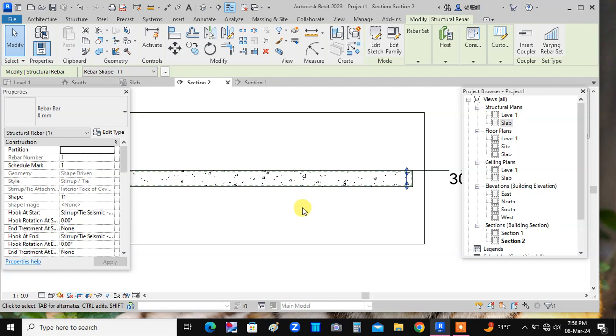Now in case of a beam, since at the end shear forces have maximum value, that's why the spacing is reduced near the support, and this distance for which the stirrups are placed closely is equal to L by 3 from its end.